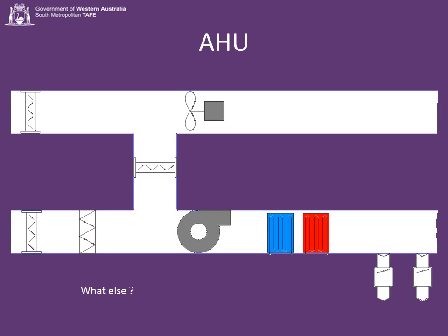So this is an air handling unit. It's a large air conditioner for a building. It works exactly the same as the air conditioning on your car though. Air that is supplied to the building we call supply air. We abbreviate that to SA, supply air, and we'd call the supply air temperature SAT, supply air temperature, supply air humidity SAH, and onwards like that.